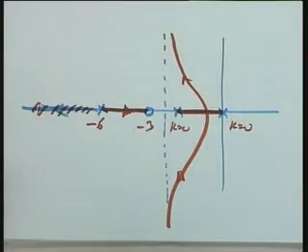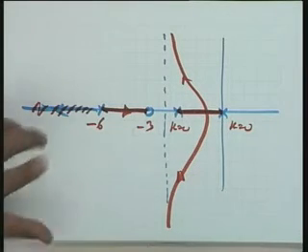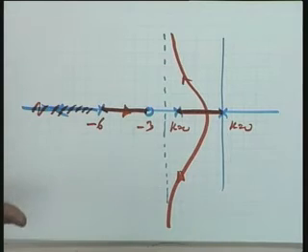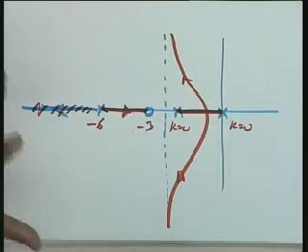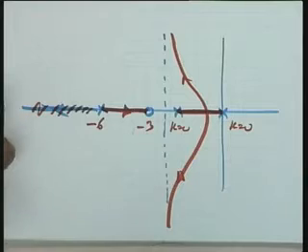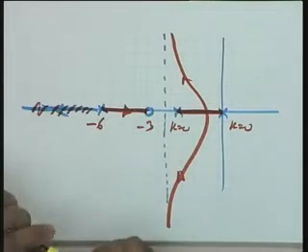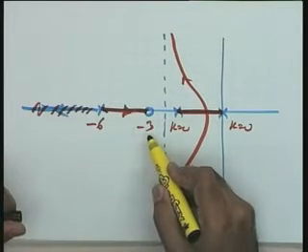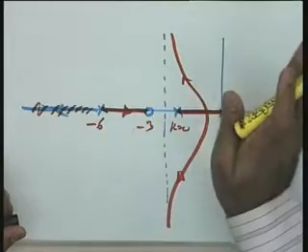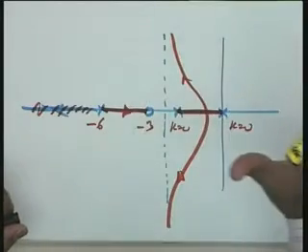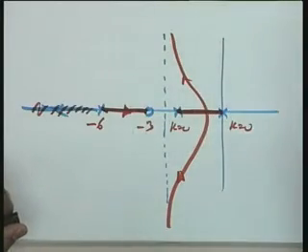You recall that the 0.105 damping ratio was very poor, the system was oscillatory. So to make it a better damped system, I have added a 0. So can we say that this particular 0 is equivalent to adding damping to the system? Or in your own terms, it is equivalent to a PD compensator, a proportional derivative controller.